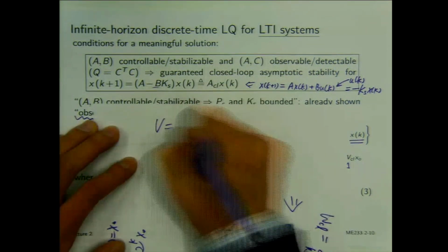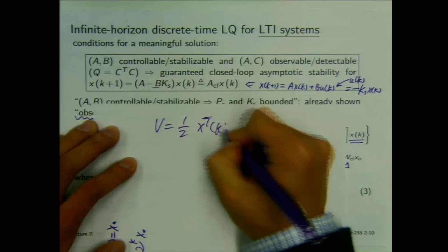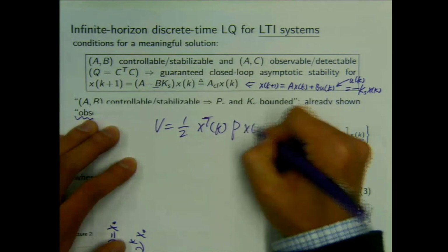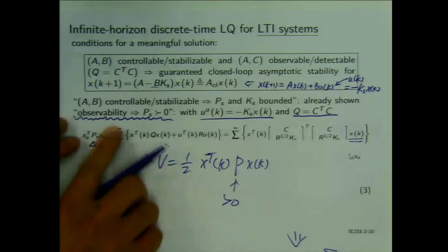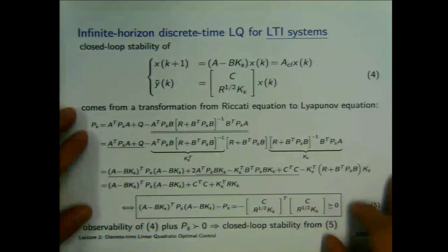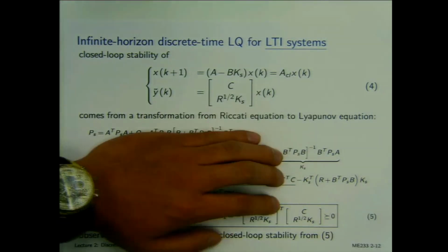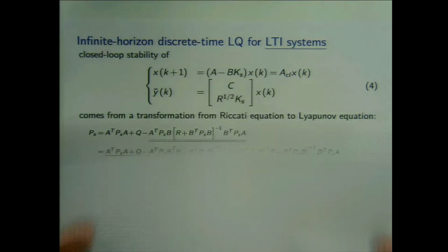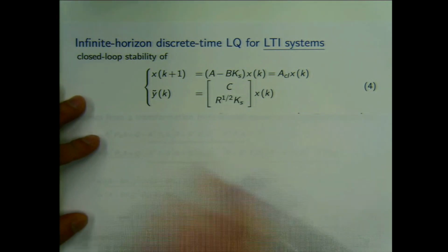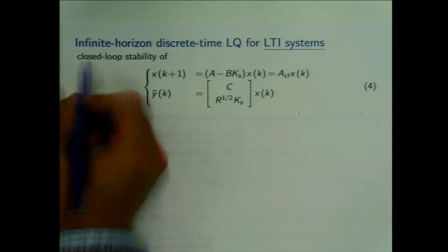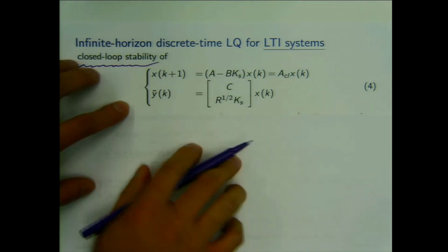Now, P. We want this one to be positive definite. And this is exactly what we have done here. And if this happens with certain additional conditions, you can guess the closed loop system is going to be stable, right? Because we can find a valid Lyapunov equation. Coming back, the first two statements are the tool sets to conclude the closed loop stability of the system over here.